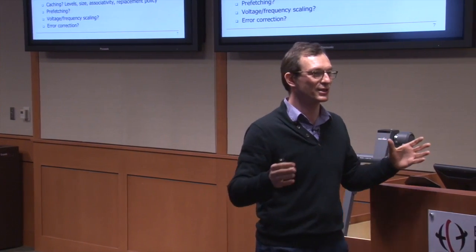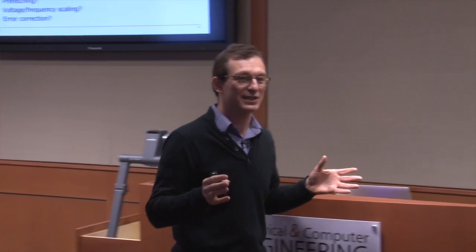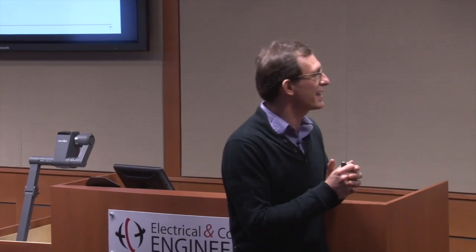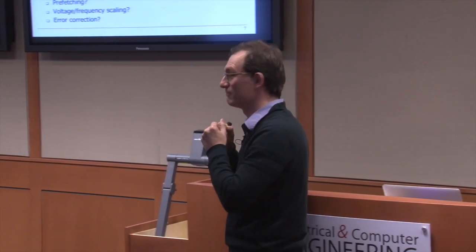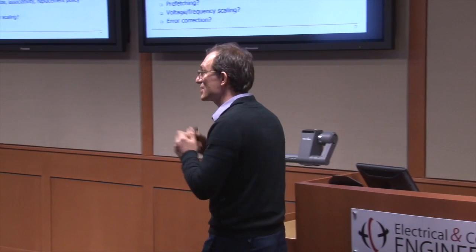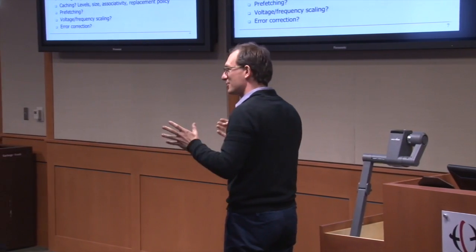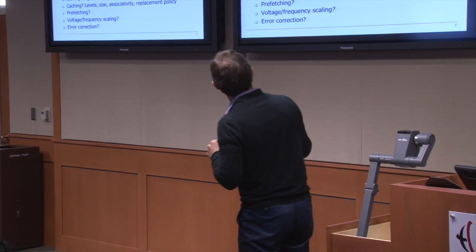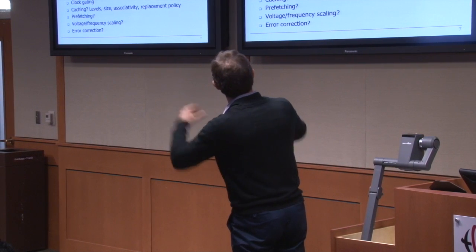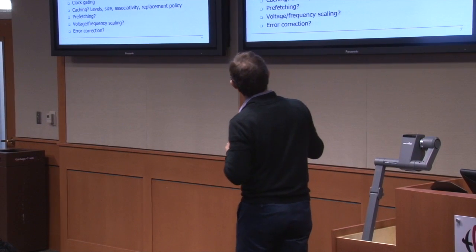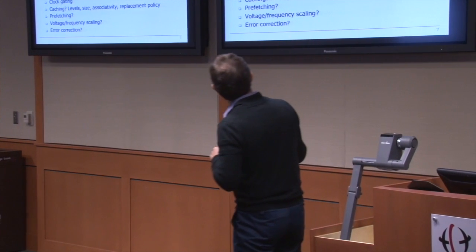If you want to reduce the latency to memory, a lot of microarchitectures today actually predict what location will be accessed later and preload that data into the cache. So that's not exposed to the programmer today. Actually, that could be, potentially. That's the prefetching part. Speculative execution is a more general term. Prefetching is an example of speculative execution, and there are many, many other examples.